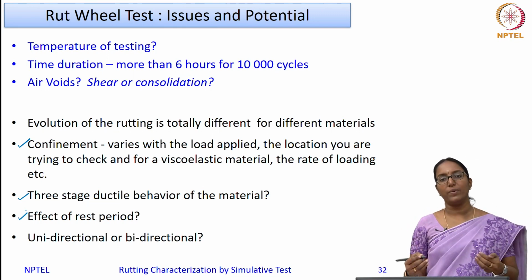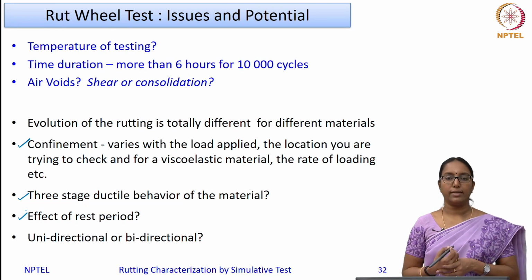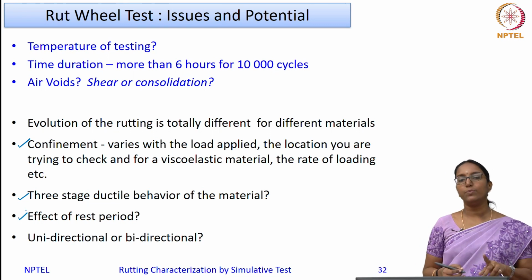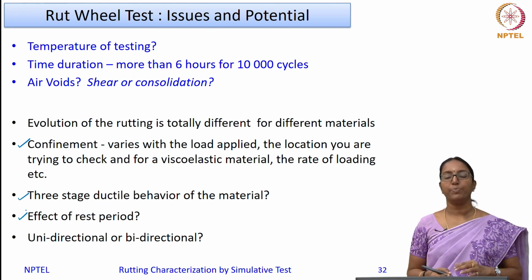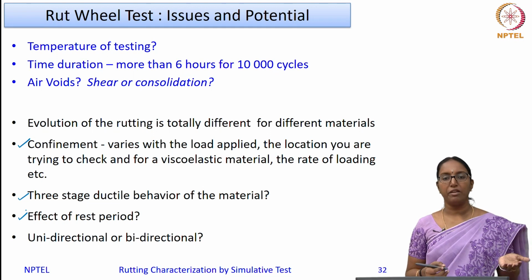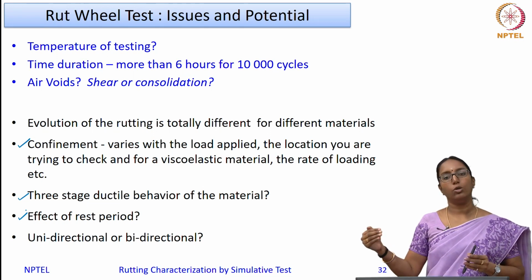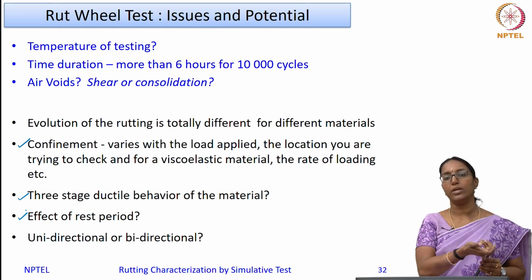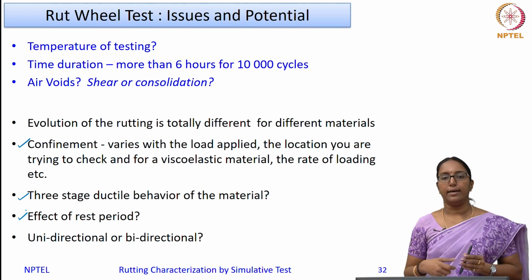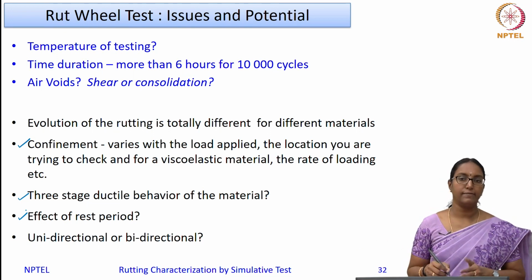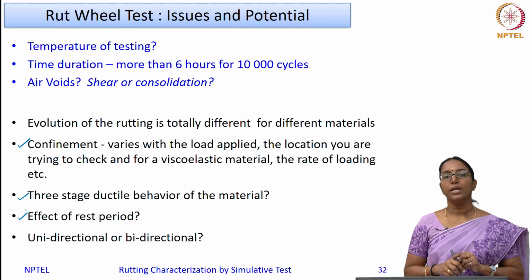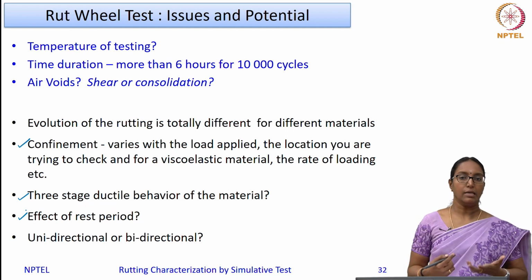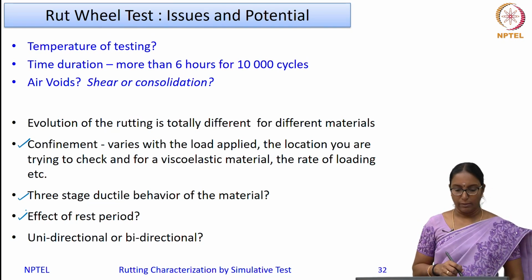So during this rest period, there could be recovery of deformation, but that recovery is not considered in this kind of test, especially when it is done in a bidirectional way. As you have seen in the accelerated loading facility, the wheel is loading in one direction, and in the second direction you have lifted up the wheel and the loading is not done in the other direction. Whereas in a simulative test using a dry wheel tracker, the loading is done in a to and fro motion. So there is no rest period being given to the specimen.